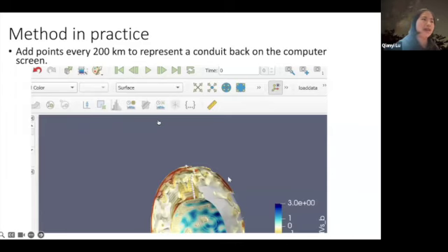And one thing that is very nice about the ParaView VR interface is that whenever you add a crop plane in the VR interface, it automatically applies it to all the data that you show. Versus if you are only using ParaView on the desktop, if you would like to apply the same crop plane to different data, you would need to apply it one at a time.